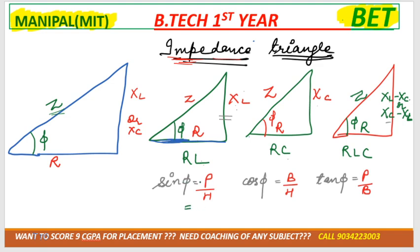Yeah, so if I want to calculate sin phi, I'm taking XL minus XC as the standard one. So you can do it the same way. That is perpendicular over hypotenuse. That would be XL minus XC by Z. Cos phi would be R by Z. And tan phi would be XL minus XC by R. Yes or no?